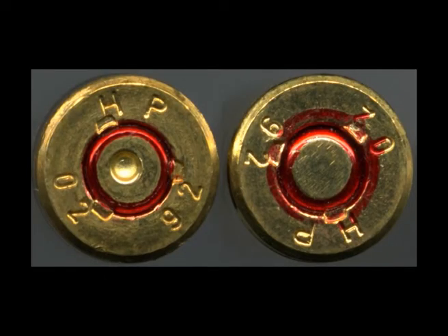On examining those micrographs, he came to the conclusion that the cutter employed for producing rifling within the barrel of the firearm will never leave exactly the same markings in subsequent excursions through the barrel. These markings, which by inference must be unique to that barrel, are then imprinted as a series of striations on any bullet passing through that barrel. He thus reasoned that it is possible to identify beyond reasonable doubt that a fired bullet originated from the barrel of a certain weapon and none other.